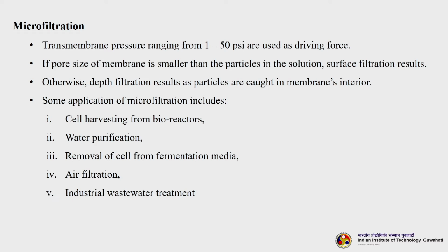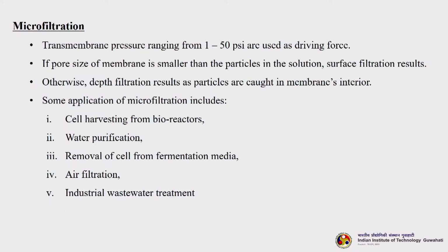Otherwise, depth filtration results as particles are caught in the membrane's interior. What will happen if the solute sizes are smaller than the membrane pore size? These particles or solutes will pass through the pores of the membrane, so some of them will go through to the permeate. Some, due to the various shapes and sizes of the pores, will be retained inside the membrane pores, thereby creating internal fouling. Some applications of microfiltration include cell harvesting from bioreactors.